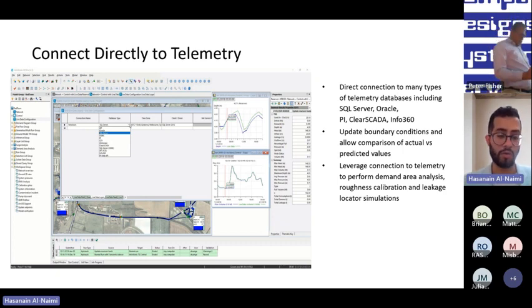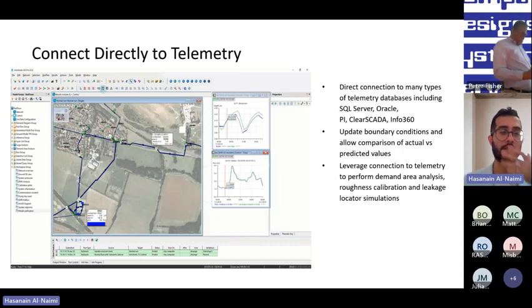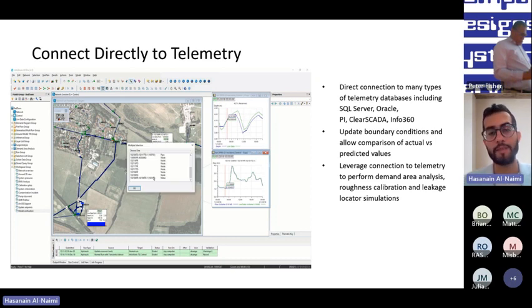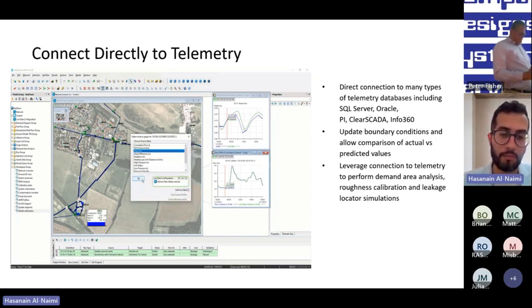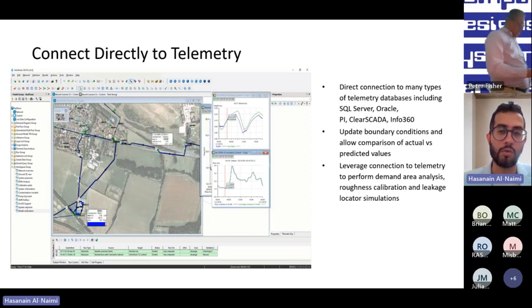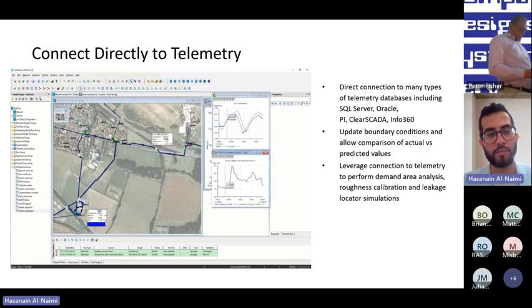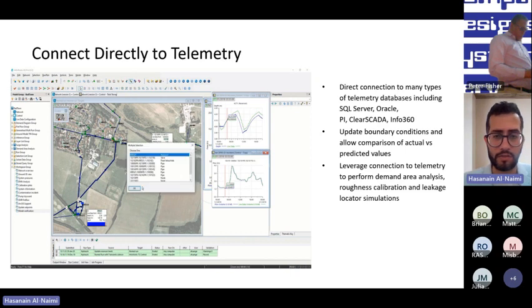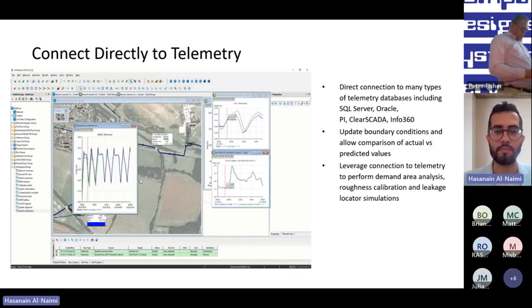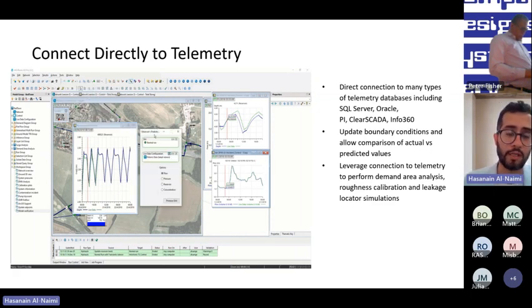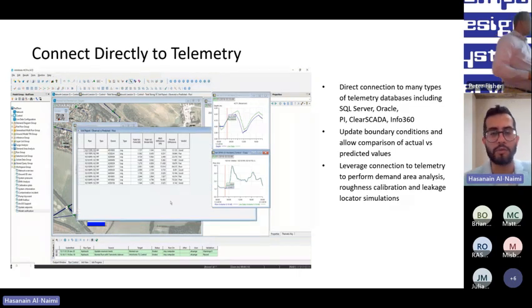One of the things Misbah mentioned is that some of these tools might be a bit advanced, maybe for the region, but the reality is you can start from anywhere. I have some customers in Africa who barely have any sensors, so they need to calibrate their system. Of course, the calibration process becomes much more difficult if you don't have any data, right? But you can always do it. If you're looking at water quality, get some lab analysis on the water quality and calibrate your model to suit that starting point, that boundary condition.